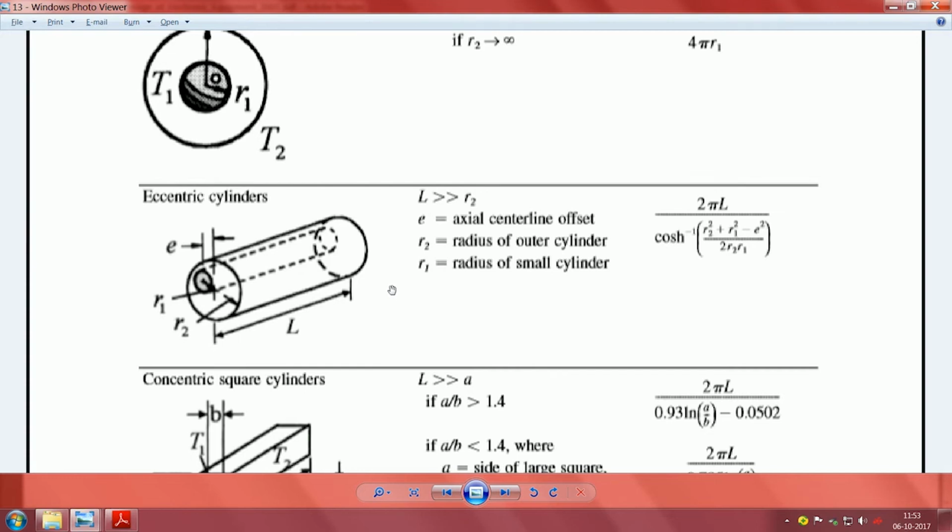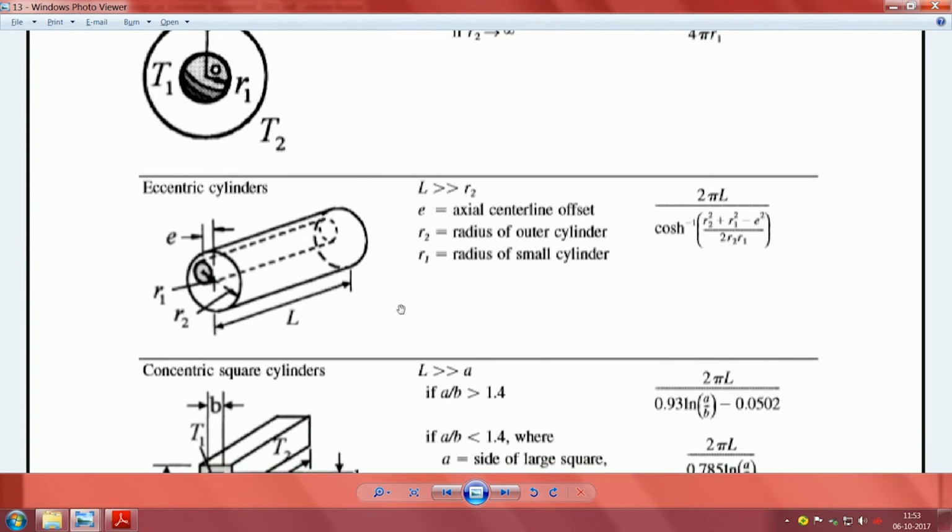If you see those large transmitters, you do have specially cut crystals which have a low drift with respect to temperature. In spite of it, they are often enclosed in a space and maintained at an elevated temperature, because cooling is not easy, and maintaining something at around 70 degrees does not degrade the crystal.